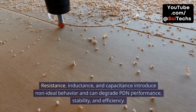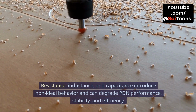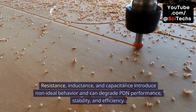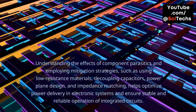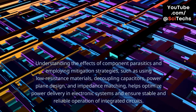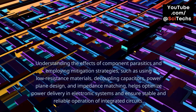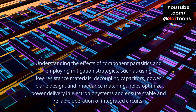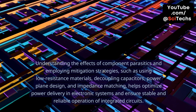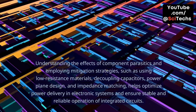Resistance, inductance, and capacitance introduce non-ideal behavior and can degrade PDN performance, stability, and efficiency. Understanding the effects of component parasitics and employing mitigation strategies, such as using low-resistance materials, decoupling capacitors, power plane design, and impedance matching, helps optimize power delivery in electronic systems and ensure stable and reliable operation of integrated circuits.